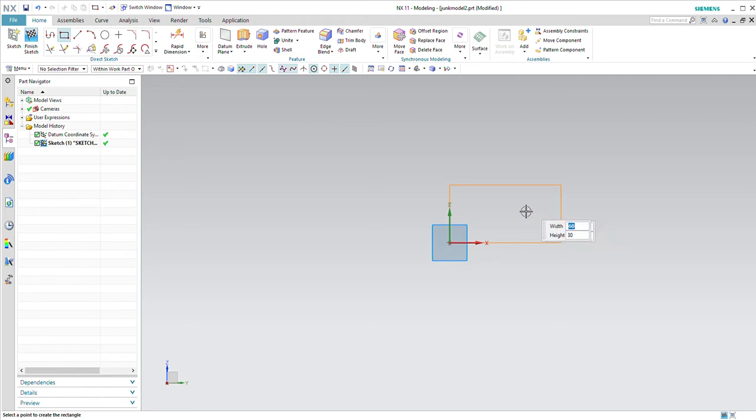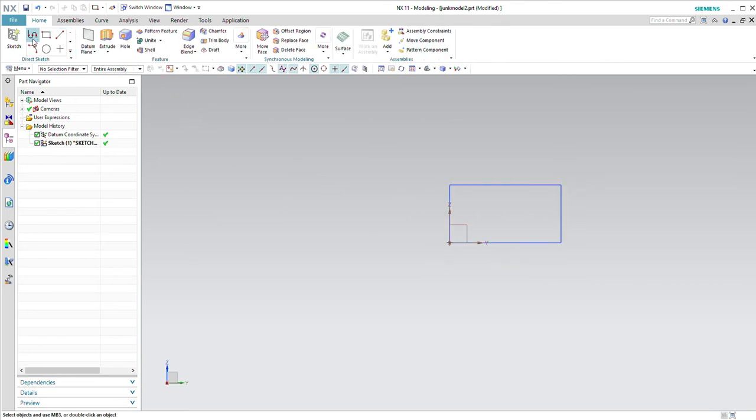So now I have the box. Right now, my box, oh, it's all set. Okay, I hit enter. Nope, it's doing it. Okay, see, that's what I wanted to show you. It doesn't tie the box down until I click somewhere. So I want the box to be in this quadrant. So I'm going to click the mouse there, and now I have my box. All right, I'm done with this. I'm going to say finish sketch.